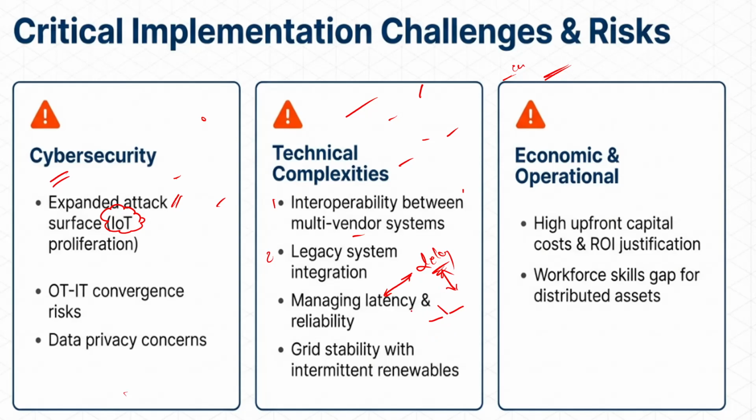So we have to create a system so that the latency is very low. Let's say in industrial standards we have a latency of 100 milliseconds, or if we have 10 milliseconds latency, it's really good. To achieve this latency of 100 milliseconds or 10 milliseconds, you have to choose your components, the sensors, the switches, which can be IT switches, the routers, to take the digital data to the database. You have to design it in such a way that the latency is very low.